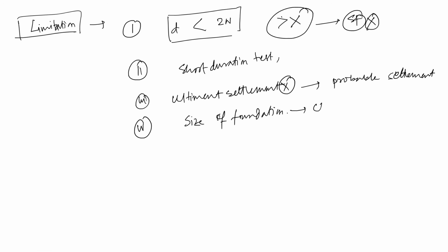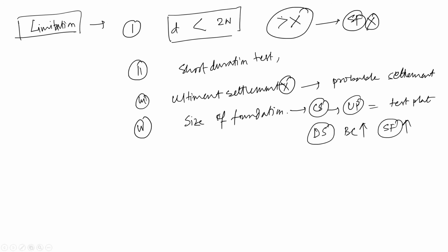And last but not least, size of foundation is a limitation. For clay soil, the ultimate pressure of the foundation is the same as for the test plate. Whereas in dense sandy soil, the bearing capacity increases if the size of foundation is increased. So there is some limitation in this test.